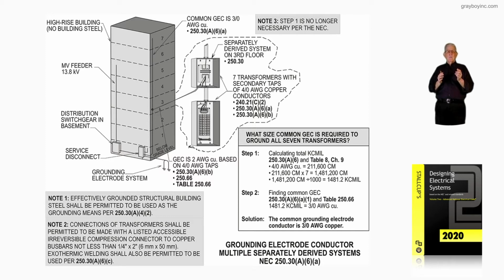So that's why sometimes you need a bus bar, to reduce as much as possible the resistance between the 7th floor and the 1st floor. You want that impedance reduced to where noise doesn't become a problem. So either use a 250 kcmil conductor, if that's what your designing engineer wants to do. You have to figure that out based upon the IEEE Emerald book. It gives you a good illustration of that.